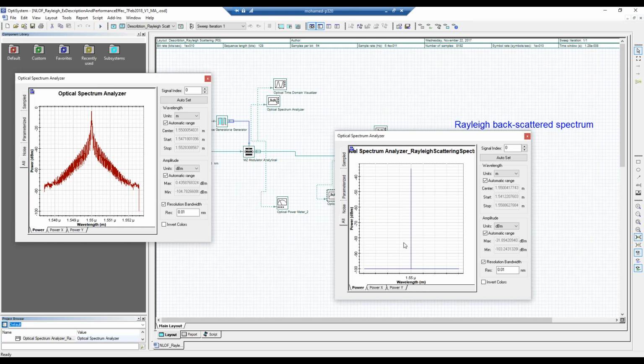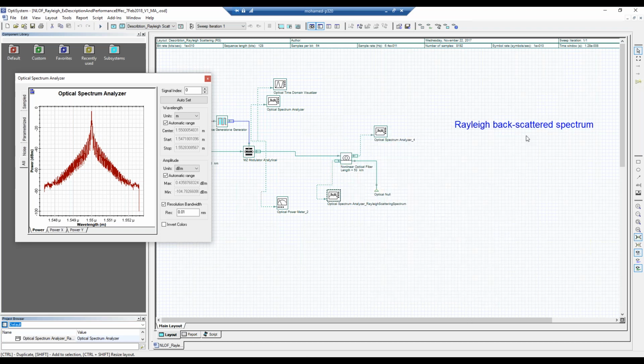As you know, OptiSystem can deal with different kinds of signals. Sampled signals mean frequency and time domain. Parameterized signals, we took the average, and they are only treated in the frequency domain. And the backscattering signal here is centered at the same frequency. That's why it's elastic scattering.